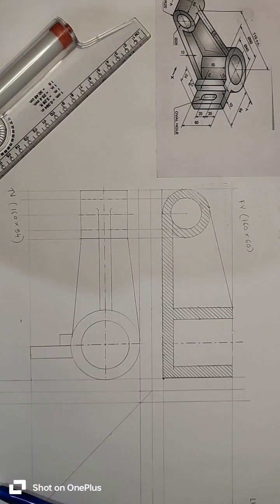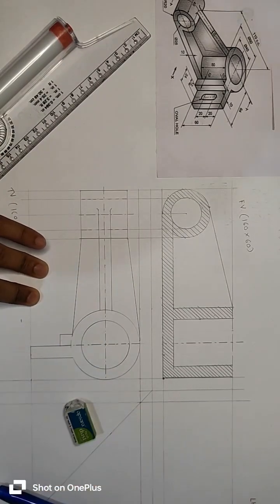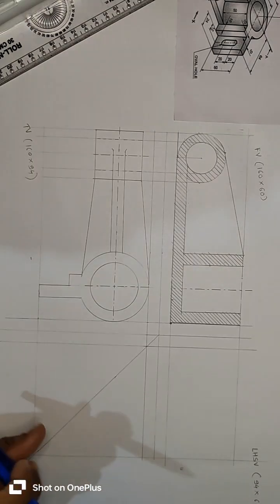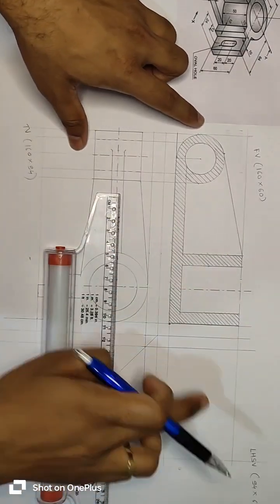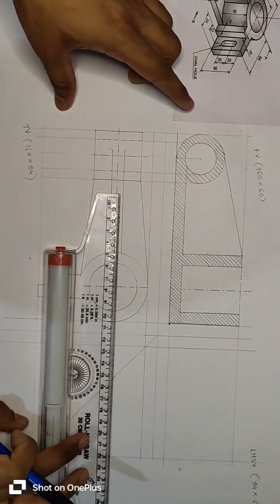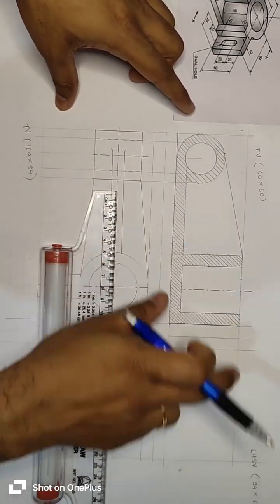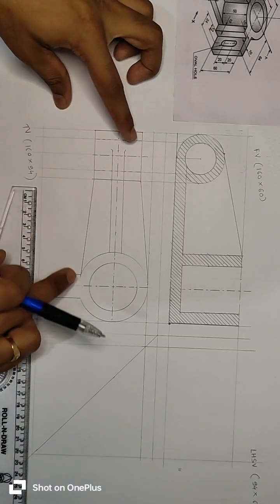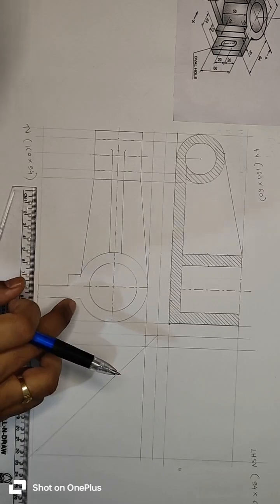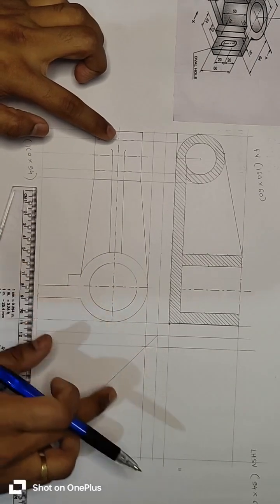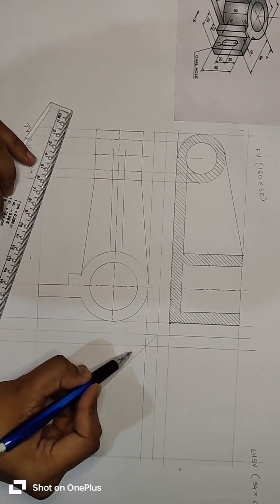Now we will draw a front view. Before that, remove this part. Now the side view is drawn by taking the projection of the front view and top view on the side view area. So take projection of important points or horizontal lines from the front view in the left hand side view, and projections of important points of the top view and horizontal lines on the LHSV through this 45-degree inclined line. So this line is for reference.